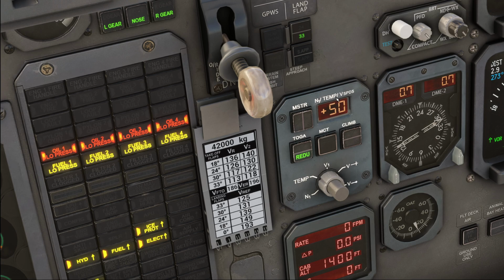If you have shorter runways, something around 30 for a runway that's between, say, 1,800 to 2,000 and a bit meters, 40 if you have between 2,000 and 2,500, 50 over 2,500, and of course all of those should take your obstacle clearance for the takeoff into consideration as well.